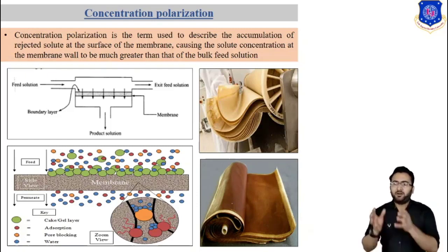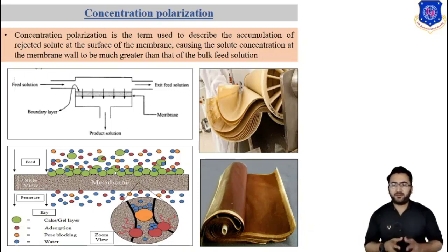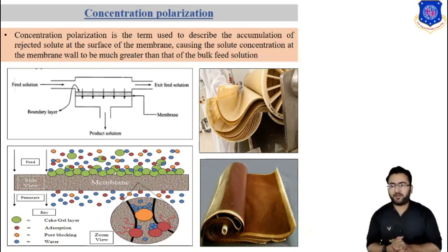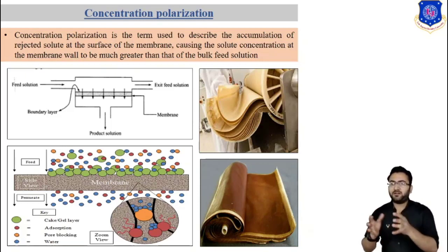Concentration polarization is one of the most important factors influencing the performance of membrane separation processes. Prediction of solute concentration polarization is crucial for designing the reverse osmosis process, predicting its performance and especially for understanding surface fouling phenomena. We know that there are mainly two types of fouling, internal fouling and external fouling. Both of these foulings occur due to concentration polarization.